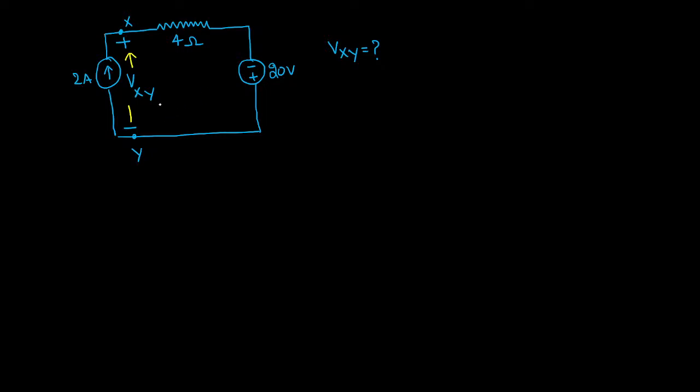So this is very simple. First of all, the given circuit is a series circuit. We are having a single loop. In a series circuit, we know which quantity remains the same. Current remains the same. That is the first logic behind this question. So if you observe, they had given a current source. That current source is supplying a current of 2 ampere. That 2 ampere must remain the same at all points, because this circuit is a series circuit.